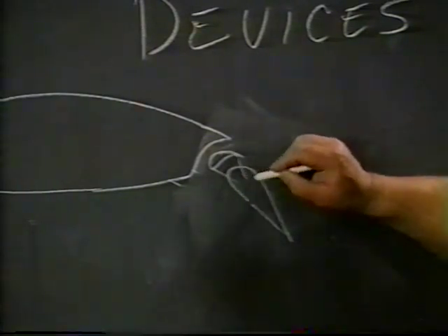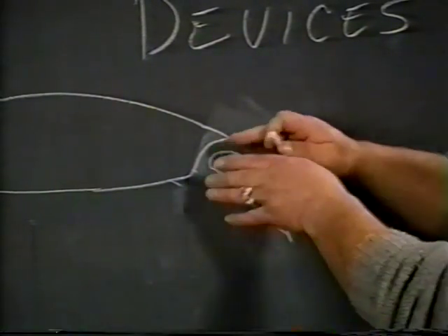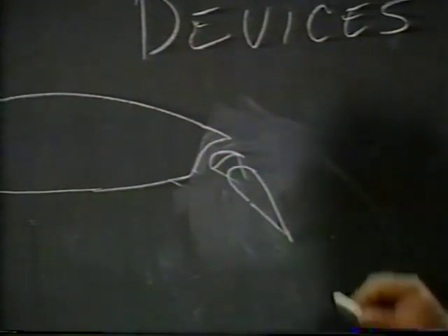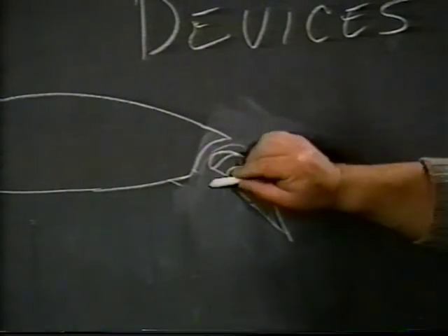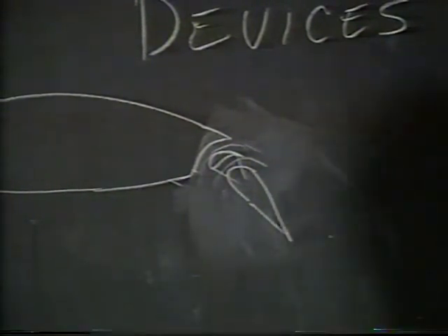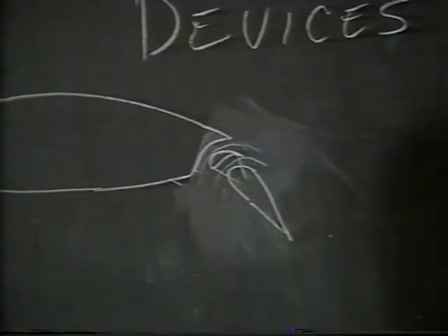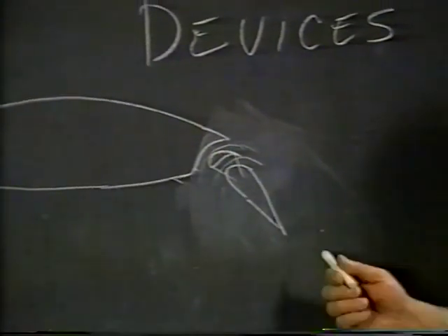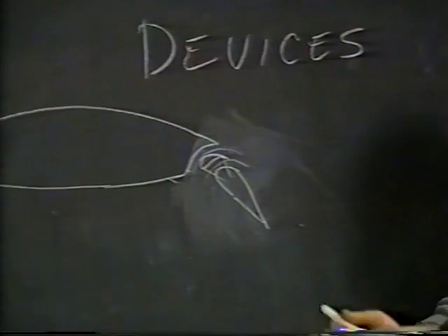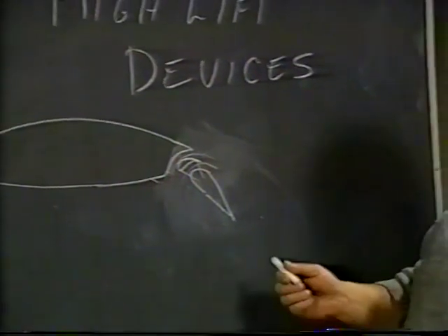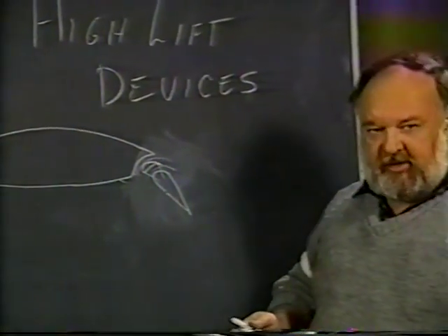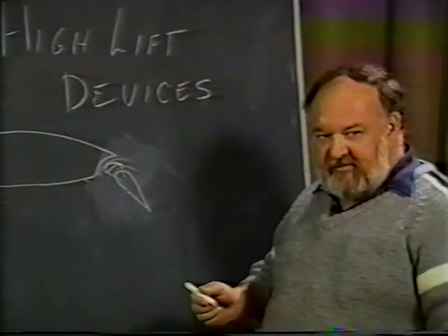This is connected directly to the flap itself. The two units work as a unit. You have one slot here and a second slot here, and that's, of course, where it gets its name, double-slotted flaps. This is a very effective flap, probably the most effective flap, based upon the total area, but it is complicated to make, rarely seen on general aviation airplanes, but very, very common on commercial airliners or military-type fighter aircraft or something like this.